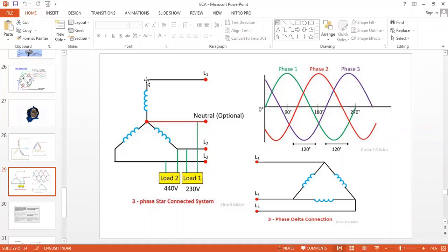Okay, so transmission lines near the poles, how many wires are we having? Basically 3 wires. If you want very low voltages, we go for an extra 4th wire, which is called the neutral. Now you see, in industries, this 440 volts is nothing but the line voltage. The voltage present between any two lines, any two phases, is called the line voltage. So we can call R as line 1, Y as line 2 and B as line 3. Here it should be L3 in the picture.